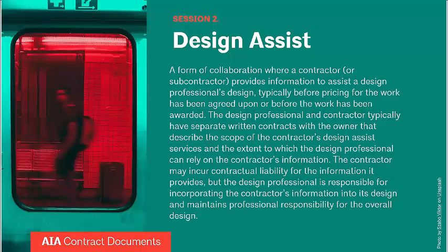Also, another thing that can be somewhat confusing that I should take a moment to address is it is very possible to do design assist services of the nature that I just mentioned, assisting the design professionals in developing their drawings and specifications, and then eventually take on delegated design responsibilities through something like performance specifications later on in the project. So you could very easily do design assist followed by, or piggybacked on, delegated design later on in the project. So we want to make sure that folks are understanding there's a difference between those two things, and you could certainly do them together, but we don't want folks to get confused if they're potentially doing one and then the other and then just calling it all one thing.